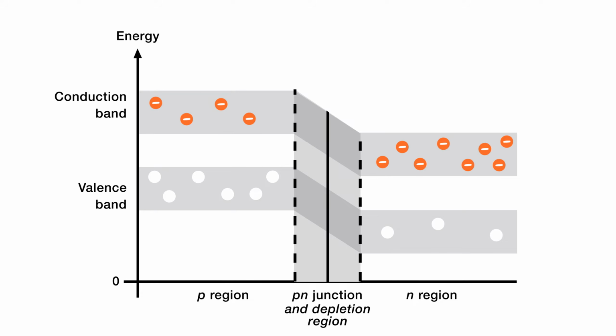From the point of view of an energy diagram, we can see that forward biasing an LED narrows the depletion region and allows free electrons to cross the junction. As free electrons cross the junction and recombine with holes, electrons release energy in the form of light. Basically, what happens inside an LED when it is forward biased is just similar to a regular diode, except that electrons release light instead of heat when they change energy levels. We don't need to discuss the reverse bias except to say that it acts like a diode when reverse biased, and if you exceed the established parameters, you will destroy the LED.